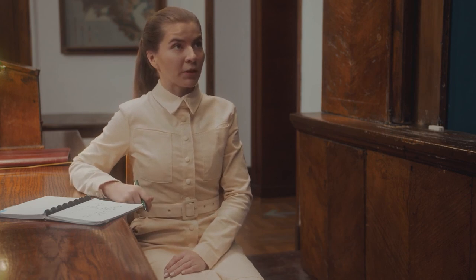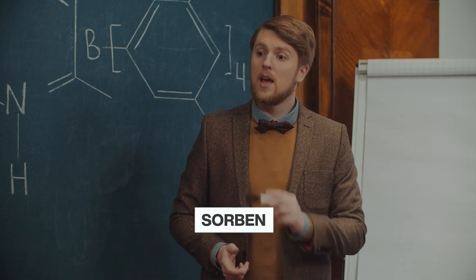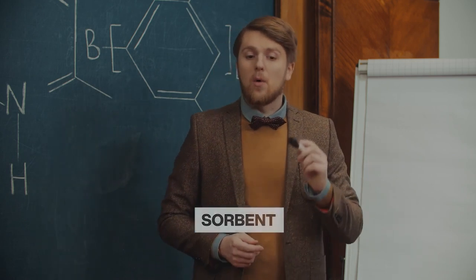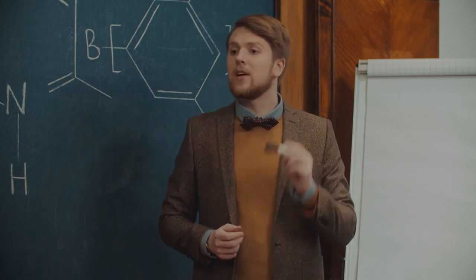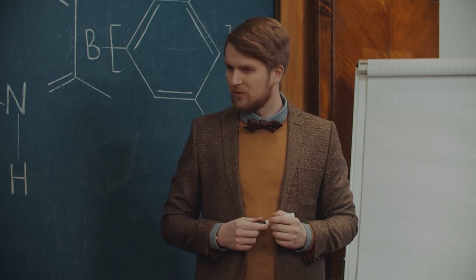Of course. Sorption can be defined as the process of fixation of various substances by liquids or solids from the environment. The sorbed substance is called sorbate and the sorbic liquids or solids is called sorbent. Absolutely right. Now, which treatment system did we consider to study the sorption process? Activated sludge. Through sorption, such treatment facilities remove...